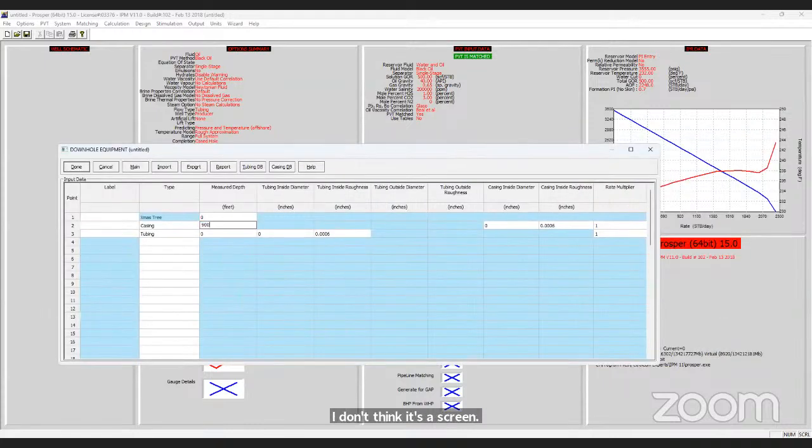Tubing, I will not reach the end of casing. I will not reach the perforation tips. I will assume that it will be 8,500. So basically, the wellbore will reach 9,000. Perforation is at a depth of 8,700. Tubing end is 8,500.